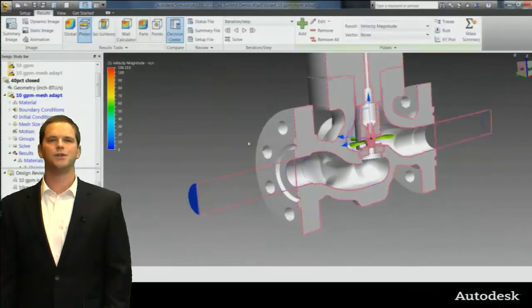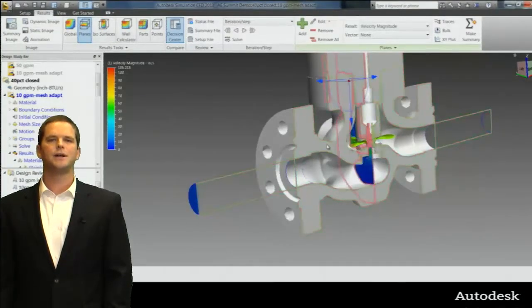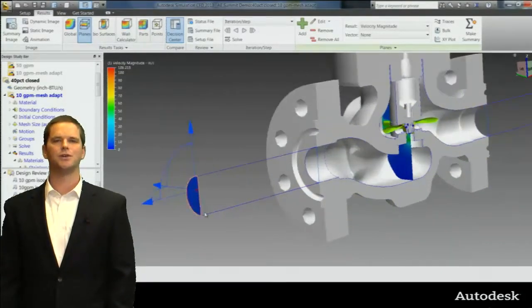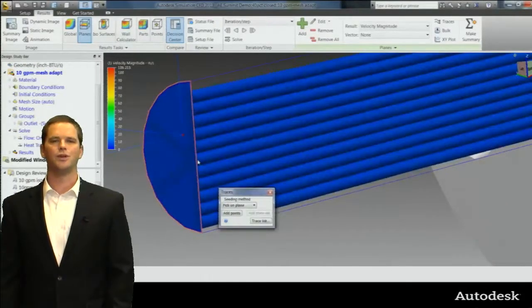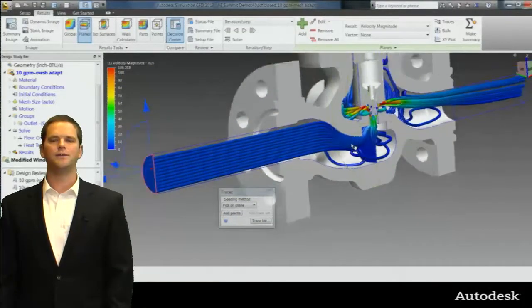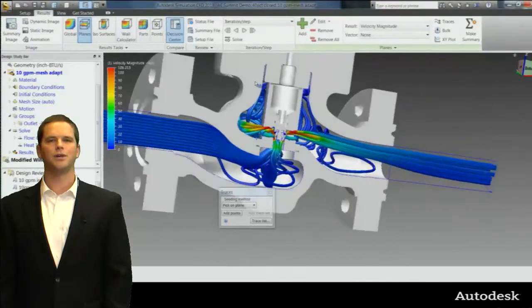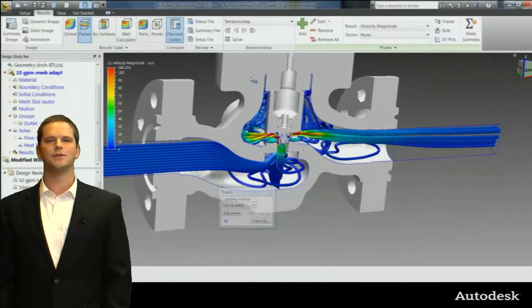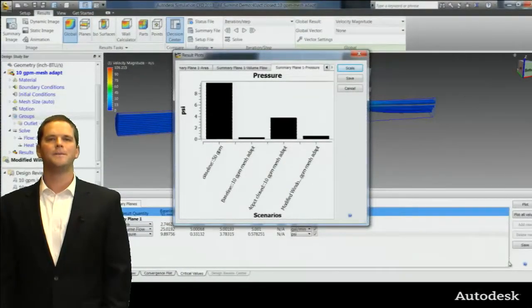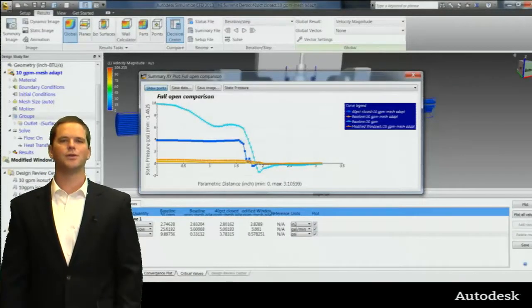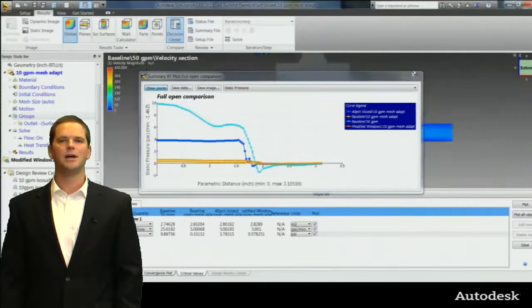But of course the most visual, impactful way to show how the fluid is moving is with trace particles or streamlines or tracers, whatever you like to call them. We can set up a grid of these trace particles and then very visually track the fluid flow through the assembly. So right here we're looking at streamlines of the fluid. We can assign mass to these as well and turn them into erosion-type particles, but it's just a really visual way to see it. So we're using graphical indication to show multiple designs and show what the corresponding effect on pressure drop is by changing the design.